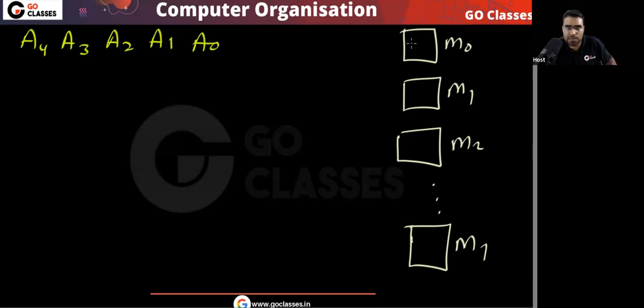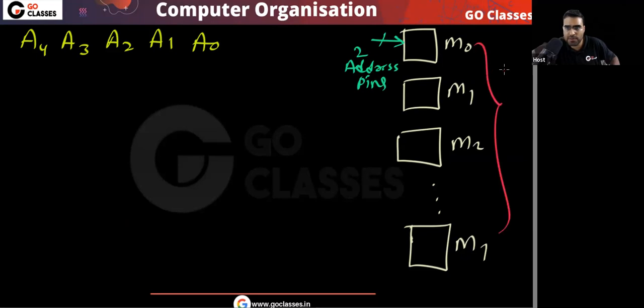In my chip there are only 2 address lines. Every chip has only 2 address pins. Now what to do? First of all, you tell me, if you have total 8 chips, then how many bits are needed to select one of them?